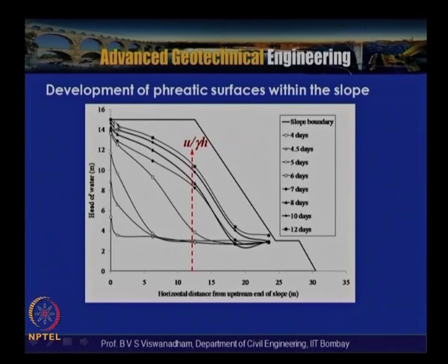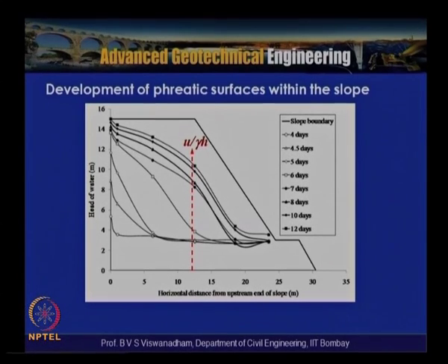The pore water pressure, for example at this particular point, continues to increase. Now, what will happen is that if the given slope is stable, with these phreatic surface conditions or top flow line conditions, the slope will be subjected to steady state seepage conditions and remain safe. But in the long term, internal erosion is one thing which can occur rapidly. So to avoid internal erosion and piping problems at the downstream of the slope, there is a need to take adequate measures to prevent internal erosion and piping at the downstream of the slopes.